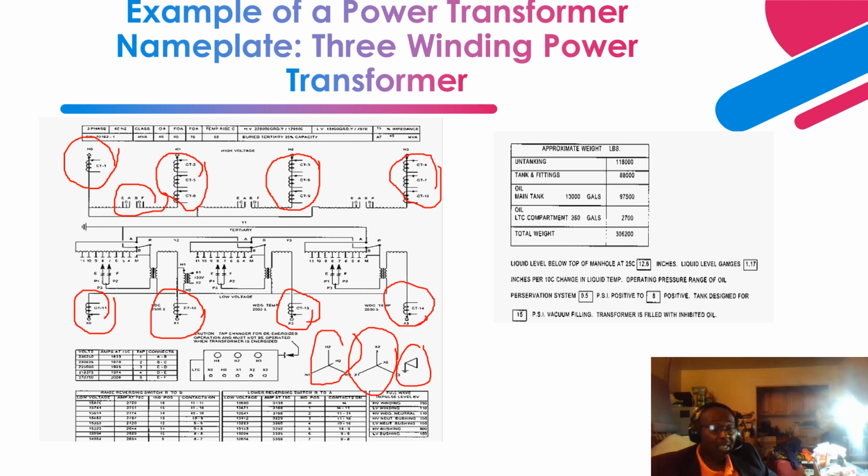This CT can either be used for protection or to mimic or determine the hotspot temperature, like I indicated in the previous slides. Basically, it measures the load current, and this load CT is integrated to a heater. The temperature of the measured heating element, plus a gradient, is added to achieve the hotspot temperature.